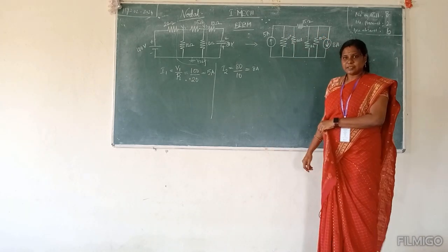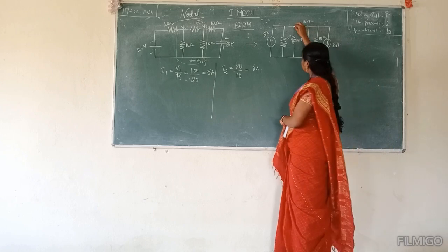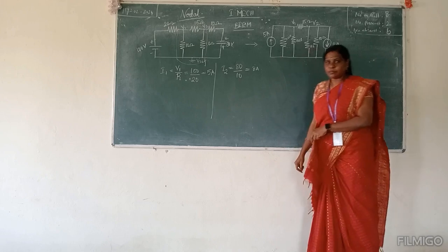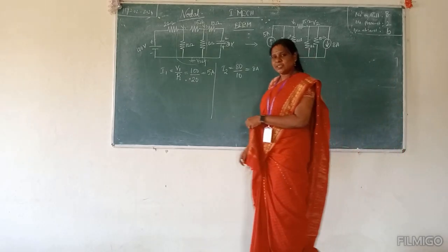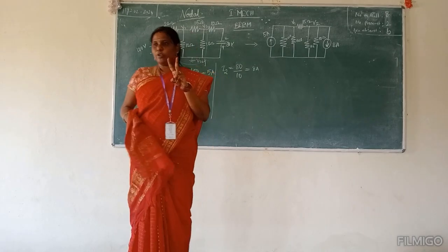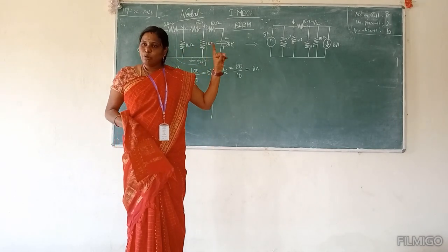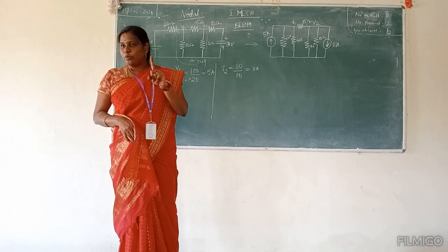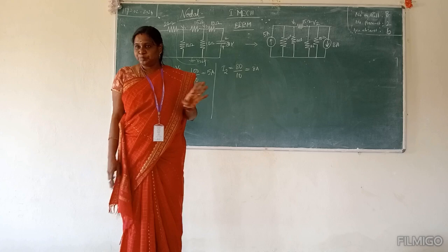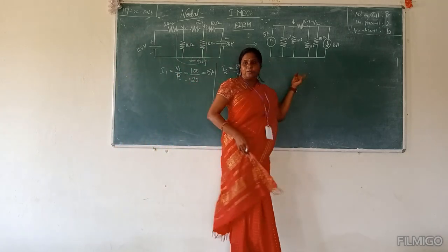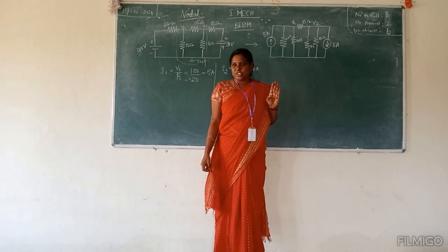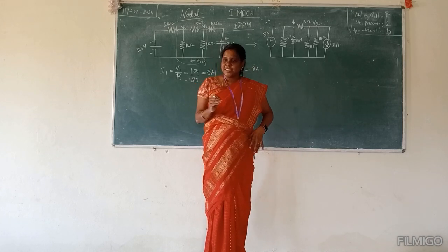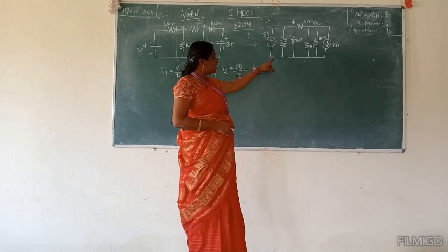Okay? Right? Now take this as V1, this is V2. If you have two nodes, then you have two unknown values, V1 and V2. You can go with the normal inspection method. Last problem we had only one node, so we directly used the equation method. Here, when I have more than one, 2 or 3, go with the inspection method, because in nodal analysis, the inspection method will be easier. Right? Up to this, clear?